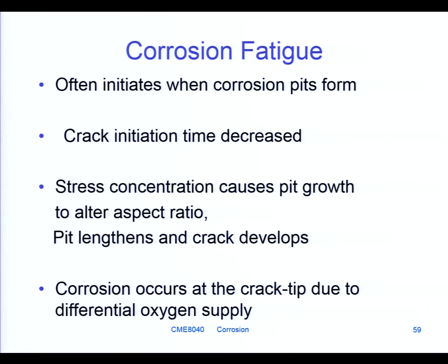One of the big things in fatigue is crack initiation time. Quite often, if the stresses are low in fatigue, you have a long initiation time before anything happens. And then if it does start to crack, the life of the component is relatively short afterwards. So 80% or so of the total life of the component may be building up slip damage in the microstructure for ordinary fatigue.